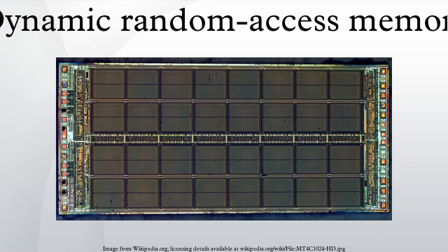Static column is a variant of page mode in which the column address does not need to be stored, but rather, the address inputs may be changed with /CAS held low, and the data output will be updated accordingly a few nanoseconds later. Nibble mode is another variant in which 4 sequential locations within the row can be accessed with 4 consecutive pulses of /CAS. The difference from normal page mode is that the address inputs are not used for the second through fourth /CAS edges. They are generated internally starting with the address supplied for the first /CAS edge.